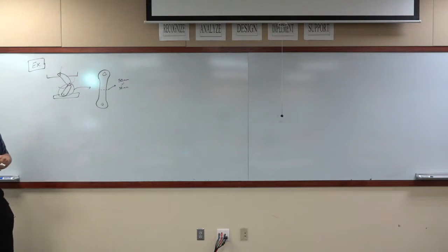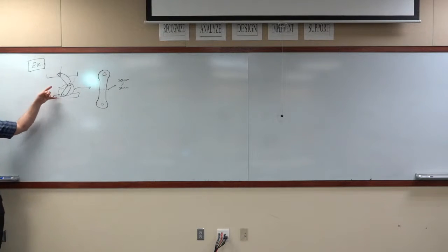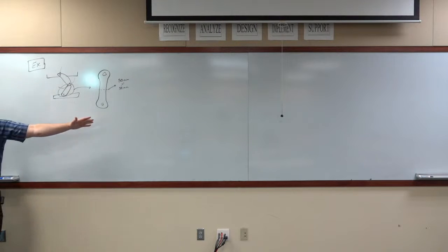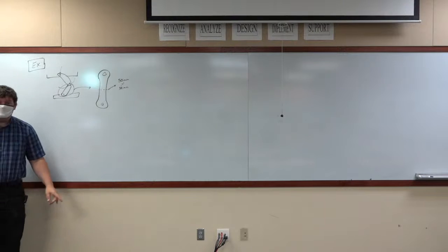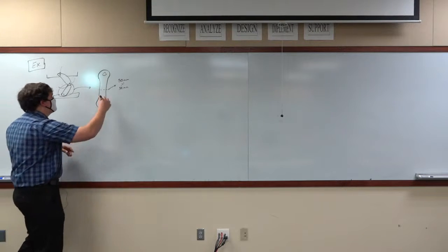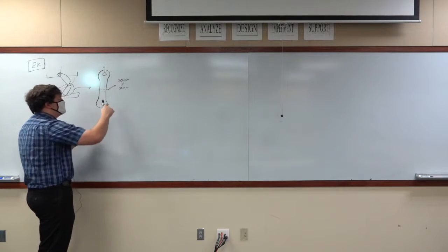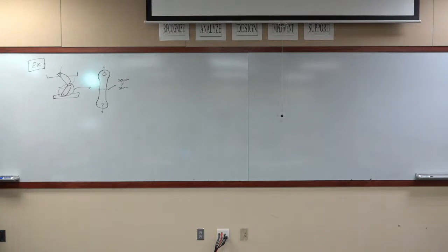Okay. What we're going to do is say that because this is a simple linkage with simple connections, simple bolted connections or simple riveted connections, you only have 2 of them, which means you know that all of the forces exerted between these are either going to be tension or compression, because those simple connections cannot exert a moment.